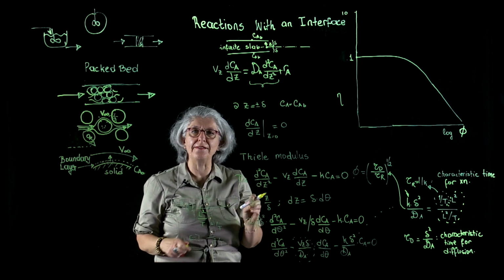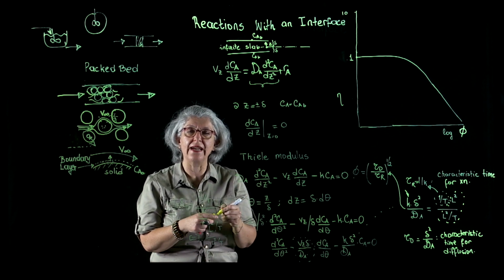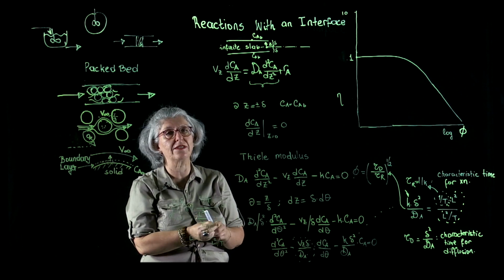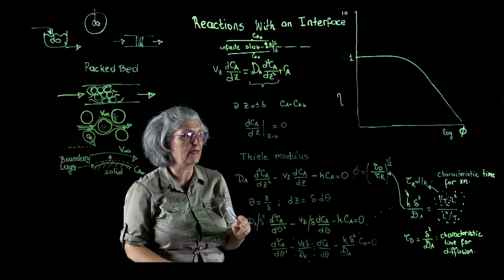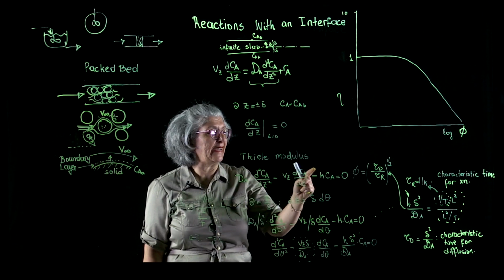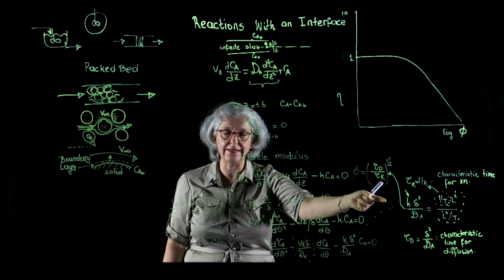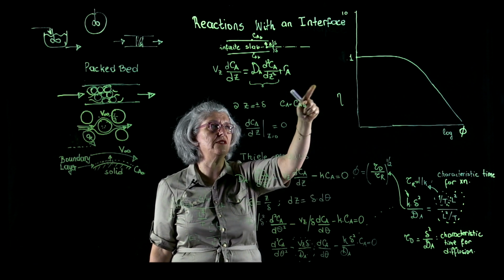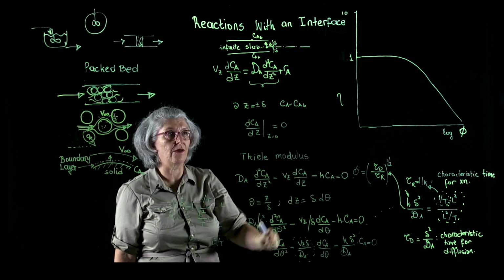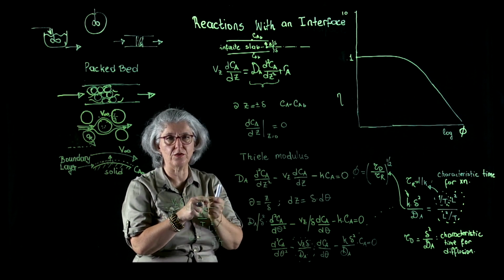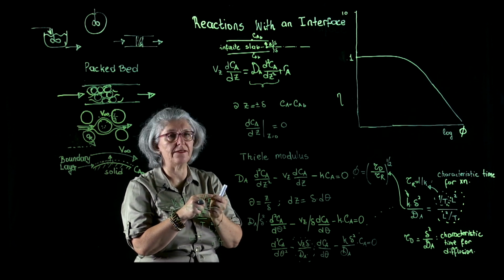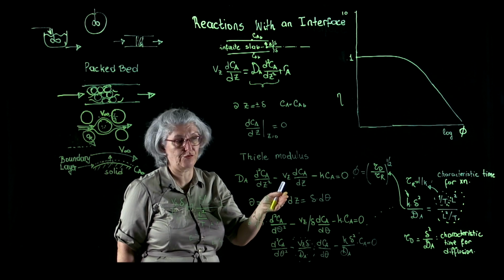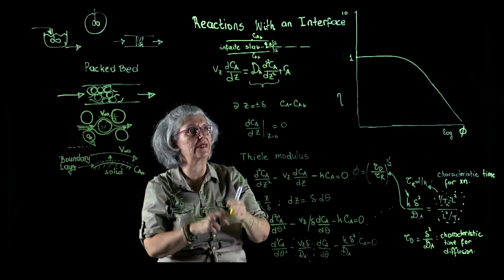So if we cannot remove the heat as fast as it is generated in such systems, and if our reaction is very rapid, we cannot do that very effectively, then our rate constant increases. So this effectiveness factor behaving between 0 and 1 is valid only for isothermal situations. Effectiveness factor decreases with temperature, of course, or if the temperature decreases.